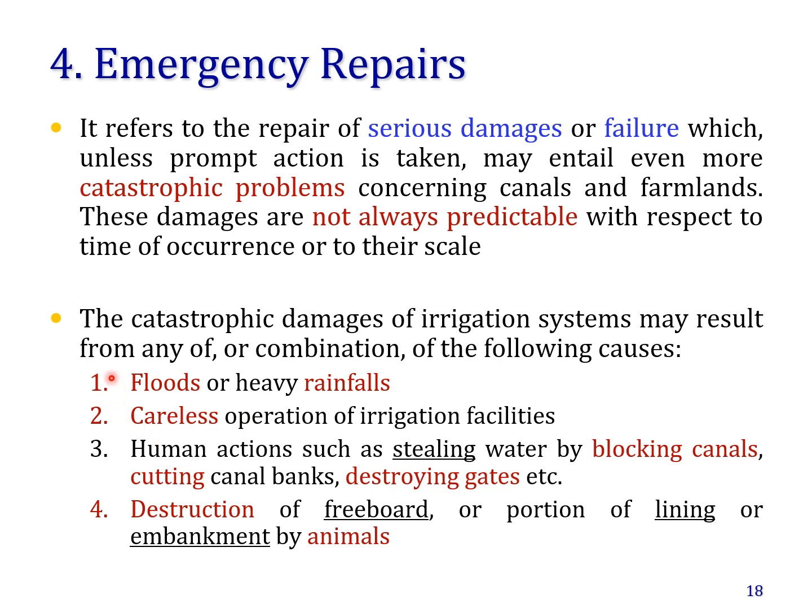Emergency mostly happens when you have floods or heavy rainfall, or sometimes the operation of the canal is being done carelessly by the staff. For example, somebody who has a duty of releasing the water in the canal may open the gates more than required, and a discharge more than the capacity of the canal would enter the canal. That can damage the canal.